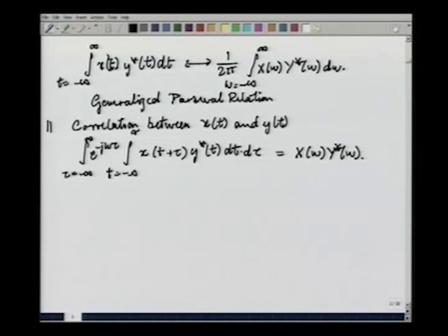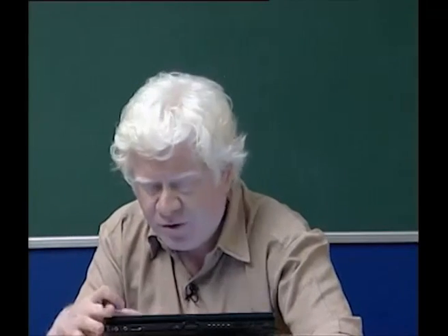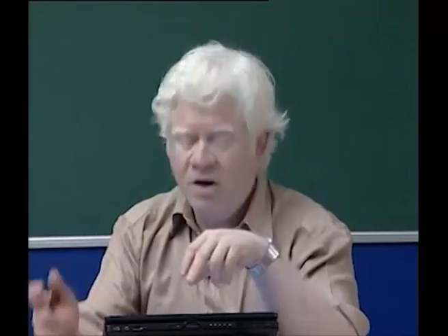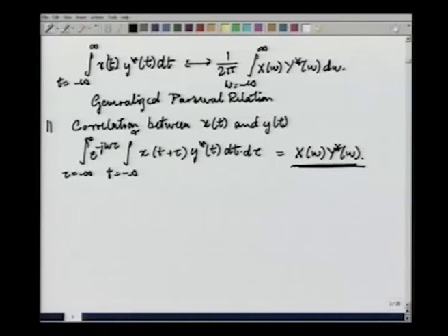Now, look at this as the Fourier transform of the correlation of two functions. That is one way of looking at it. Suppose you looked at this just as the result of a convolution. Remember, if you convolve two functions, you get a product of Fourier transforms. So, suppose I ask you now, what are the two functions of time that ought to have been convolved to get this expression? That is not hard to see.